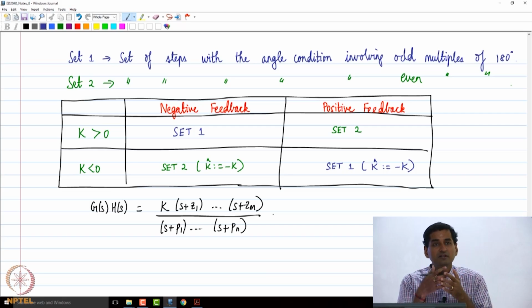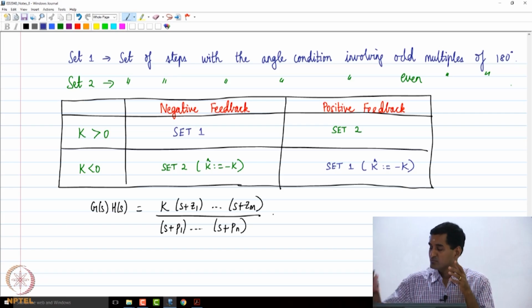Depending on your design choice, we will do a case study tomorrow that will run through the entire process. Now that we are done with root locus design, I will take a physical problem. We will start from the beginning, derive a mathematical model, get the plant transfer function, then design controllers, find out what ranges of controller gains will stabilize the closed loop system, then construct the root locus to satisfy certain performance requirements.